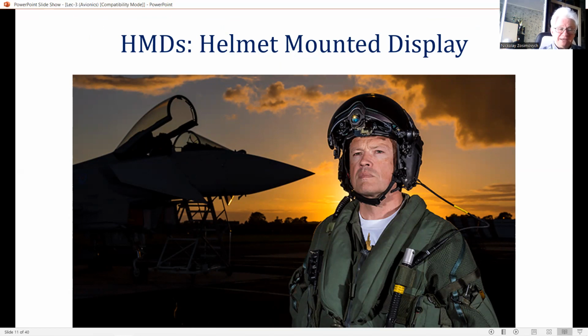of the integrated helmet system about the yaw and pitch axes of the head should be as low as possible. This is to minimize the inertial torque experienced by the pilot due to the angular acceleration and deceleration of the head and helmet as he is scanning for threats from behind or above. Peak head motion rates of 30 degrees per second can occur in combat.